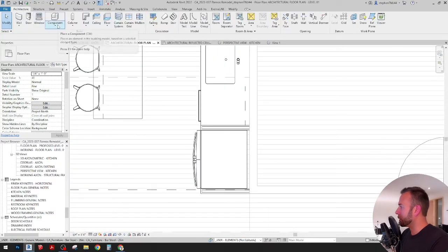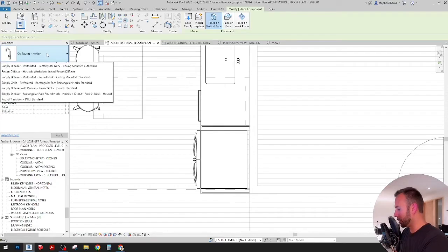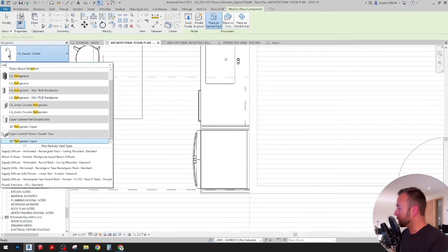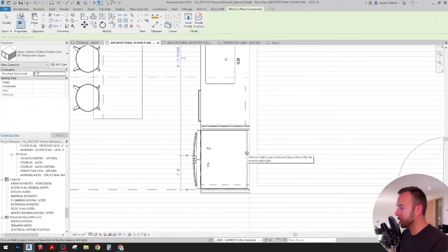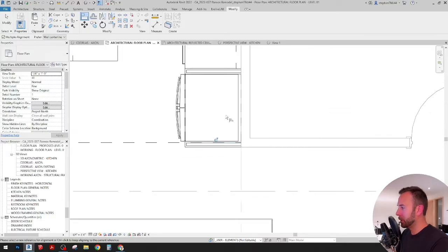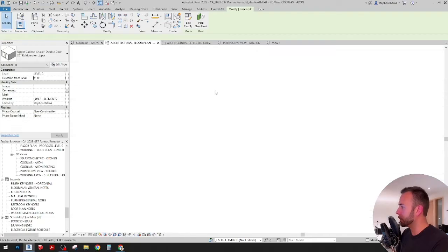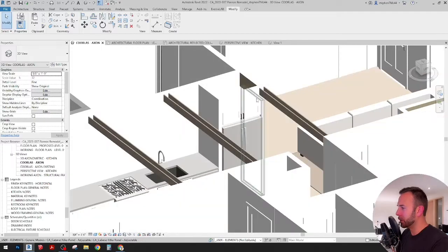and then let's tuck in the refrigerator cabinetry that goes above the refrigerator, but I believe I have it called out as, if I start typing in refrigerator, got shaker 36-inch refrigerator upper. It connects to the wall there. Just place it and then refine the placement there. And I'm not sure if that was a 2 foot tall or a 1 foot tall based on 8 foot ceiling. So let's check. That was a 1 foot. Okay, so that slips in right underneath there.